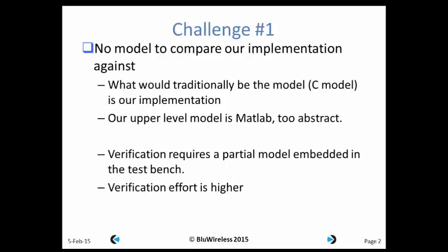This is one of our first challenges here. The way that we do our design is that we are a SystemC design, and we use C to silicon. So unlike a more conventional system, we don't have that C model to compare our RTL against. Any self-checking verification system needs to have a reference, and in our case, that isn't necessarily available to us.